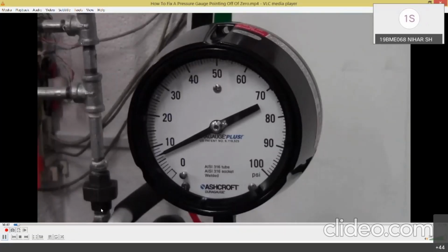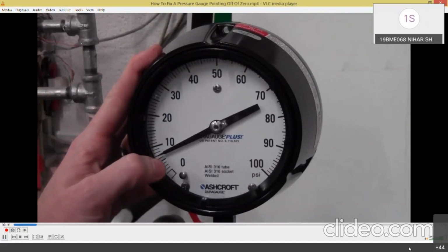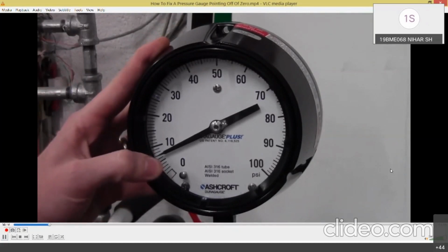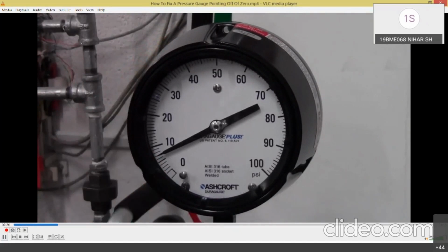Welcome back to the Kodiak classroom. In this lesson, we're going to learn how to utilize an adjustable pointer. Now, looking at this gauge, you can see that it's reading roughly around 7 to 8 psi. The problem is that there's 0 psi in the line. So obviously, this gauge is off of 0. So let's fix that. It's an easy, quick fix out in the field as long as you have an adjustable